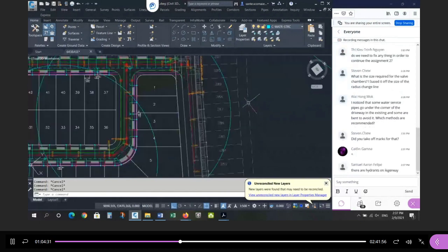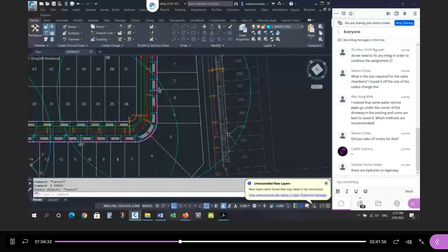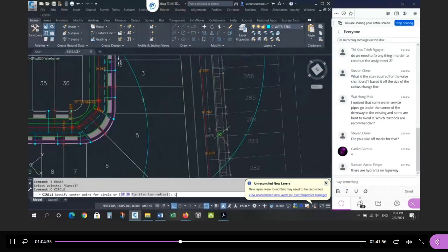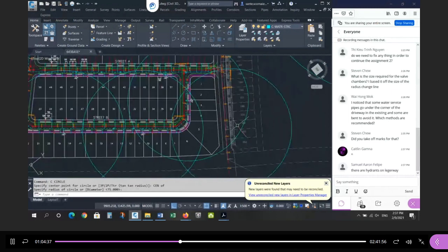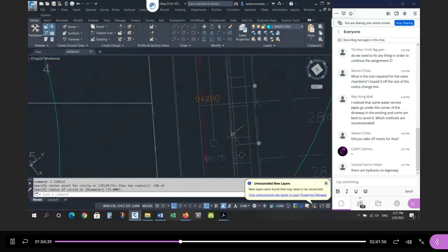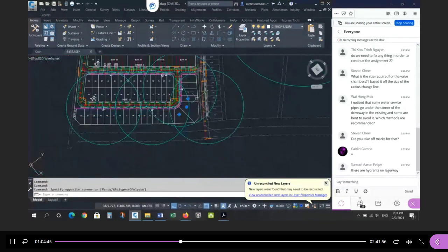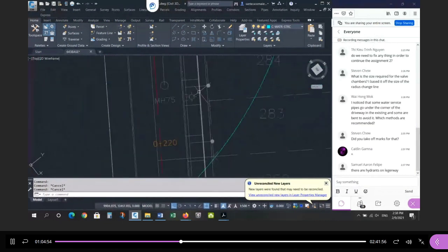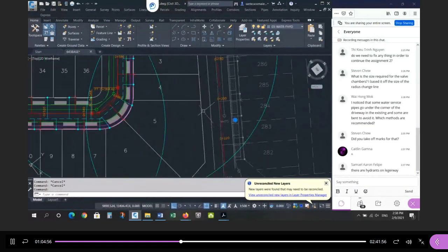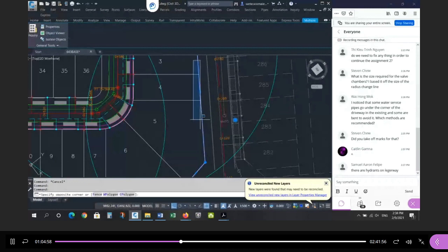The other argument, and I've had this in the past: there's a hydrant right here, right? This hydrant here covers lot 6, lot 5, lot 4, right? This circle covers these 3 lots. Everybody agree with that statement? Yeah, Samuel, this is exactly what I'm getting at. How do you get to this hydrant if this is the back of the lots and there's a fence here?